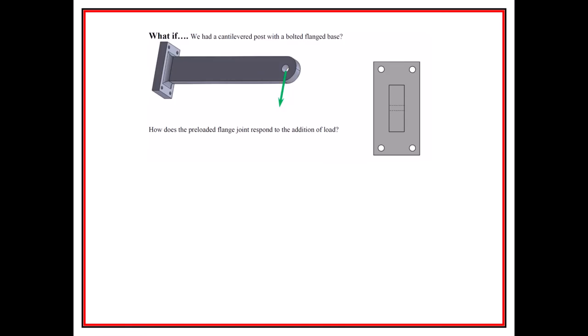One of the projects I worked on at Electric Boat was on some propellers and propeller blades, and they were faced with a pressure wave that hit them, and we used an FEA model, and it returned some loads. We could pull off loads at these little links that represented bolts, but that's not exactly the right way to represent the bolts, because the part where the blade is connected to the hub is squishy. We just learned that from our previous class. These are preloaded, so not all those bolts will feel the load exactly. There's going to be a certain amount of interplay. And so we had to come up with a certain logic for how the load is distributed in these bolts.